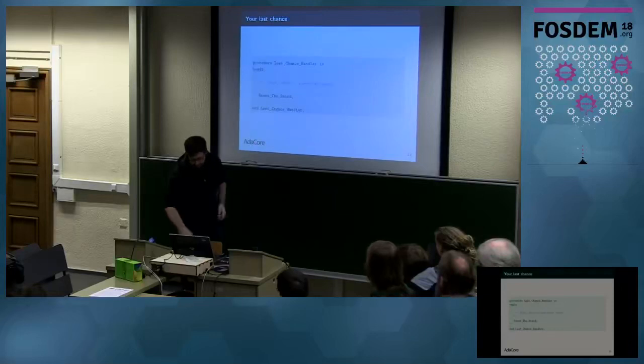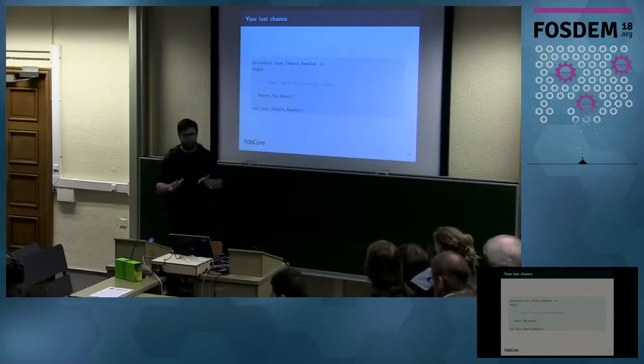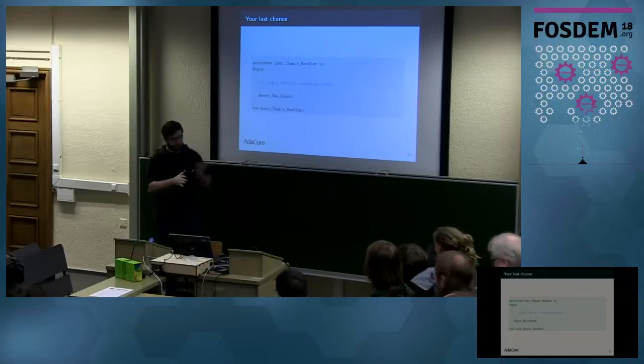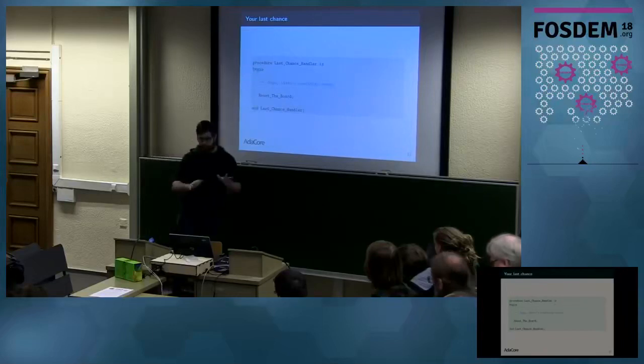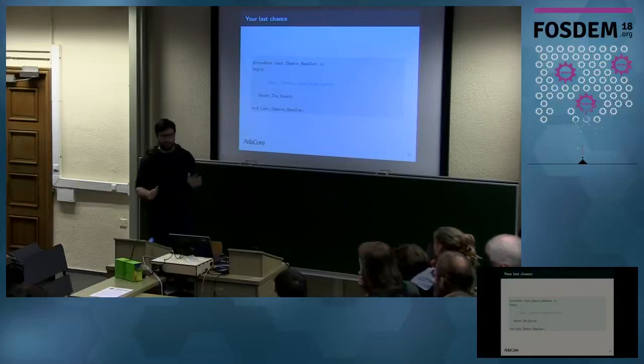The last chance is this procedure. When an exception is not handled in Ada, this procedure will be called, it's a very good name, the last chance handler, and that's your last chance to do something about the situation. Usually, when you go to this, you're in a really, really bad situation, so you probably want to shut down everything, reset the board, or maybe wait for user input, something like that. And so that's your last resort. After that, there's no more protection.